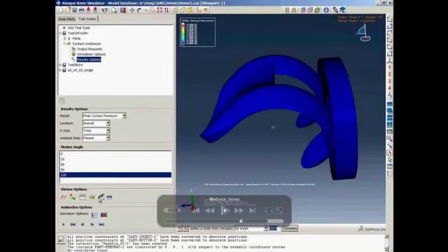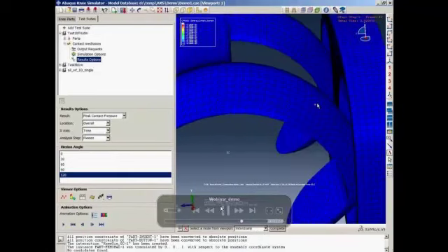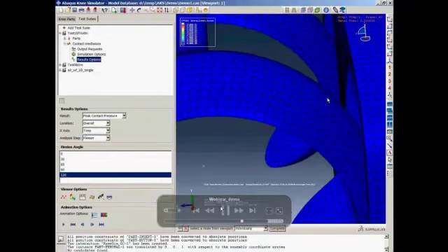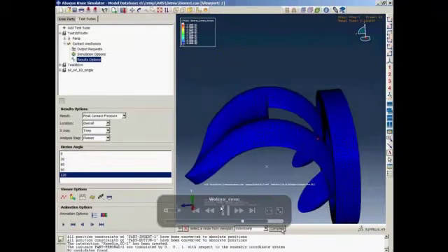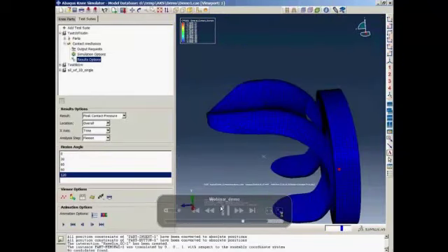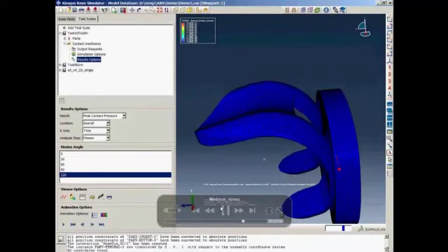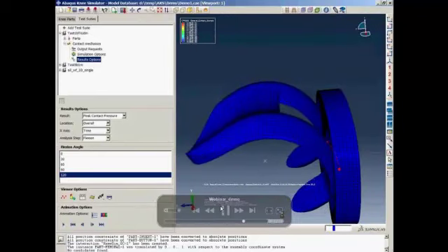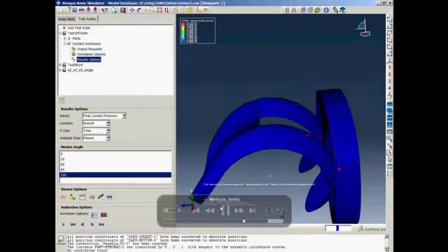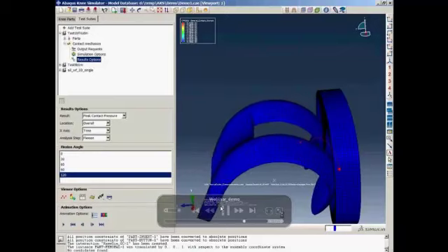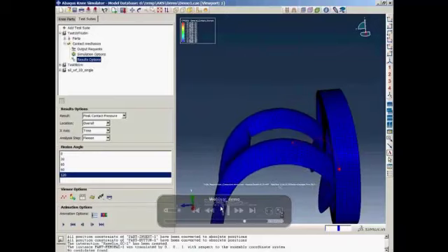It is called plot the trajectory. So the user can pick any point, any moving point on the implant components or on any ligaments or bone parts. They can pick any points here, and the knee simulator will plot the trajectory of this point during the analysis. So in this case, I picked a point close to the dwell point on the femur components, and the Abaqus knee simulator plotted out how this node moved over the flexion range specified.